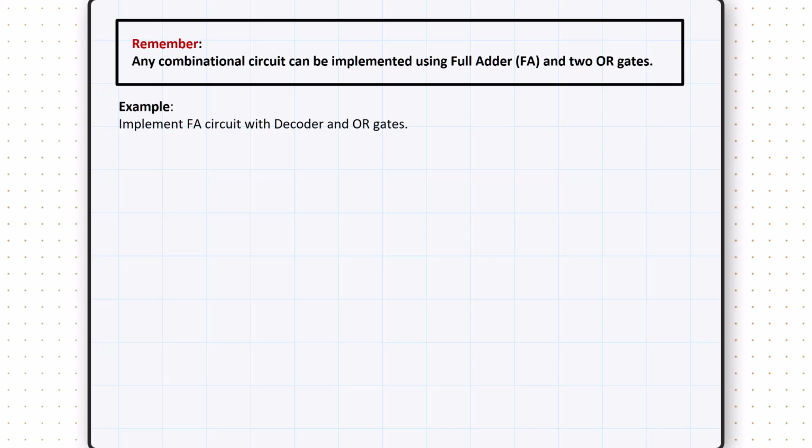So the first one, we will have to figure out the number of inputs and number of outputs. Considering that we are implementing a full adder, we already know that there are 3 inputs and 2 outputs. If we call the inputs x, y, and z, the outputs are always the same, S standing for sum and C that stands for carry. So the result in here, what we will put actually for the first step, is the following.